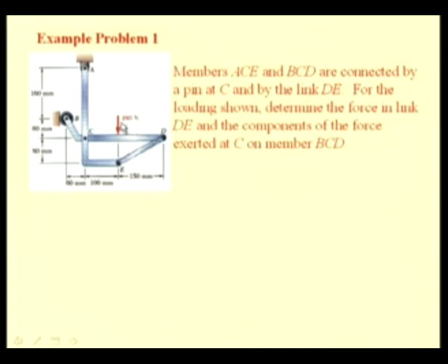Various dimensions are also given and an externally applied load of 480 newtons is laterally applied to this member BCD. We are interested in what the various forces developed in the joints and in the members are under this loading condition. Let us see first whether this frame is statically determinate. The frame is statically determinate by considering the free body diagram of the complete frame.